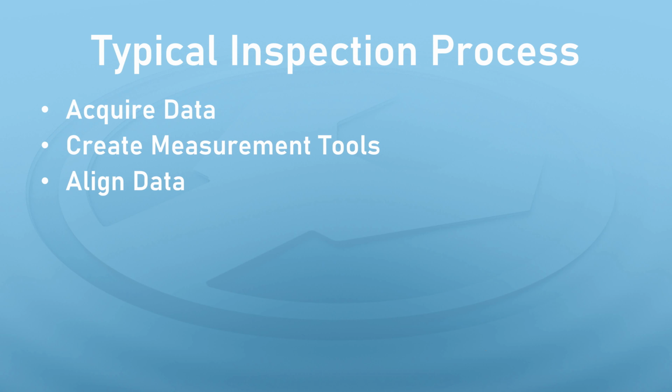Align your data. This could either be aligning data to data, i.e. scan to scan, or data to reference, i.e. scan to CAD or nominal measurements. Measure your part. This could be a matter of extracting or even probing the measurement tools that you have created.